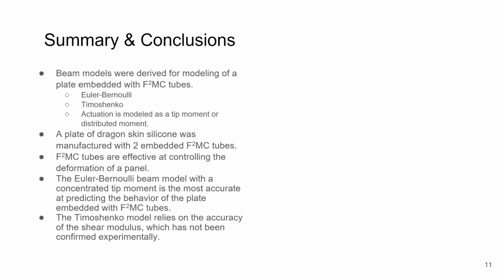The Euler-Bernoulli beam theory model with a tip moment was found to be most accurate at estimating the deflections, and the Timoshenko model, which relies on shear modulus in its formulation, underestimated it, although the shear modulus has yet to be confirmed experimentally.